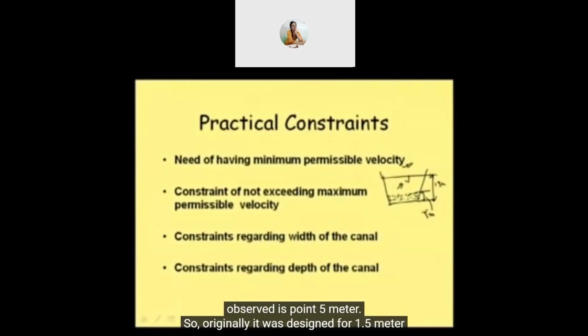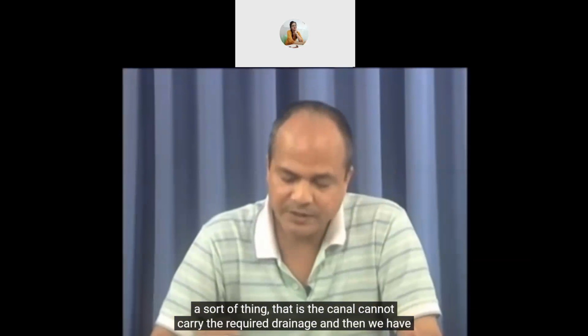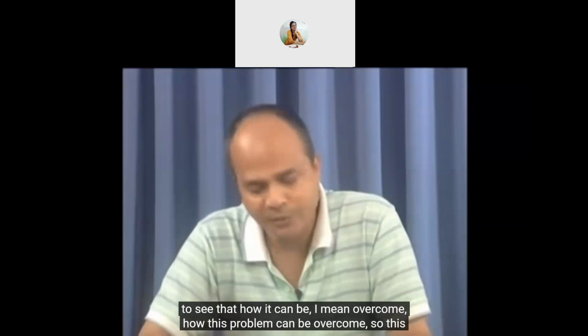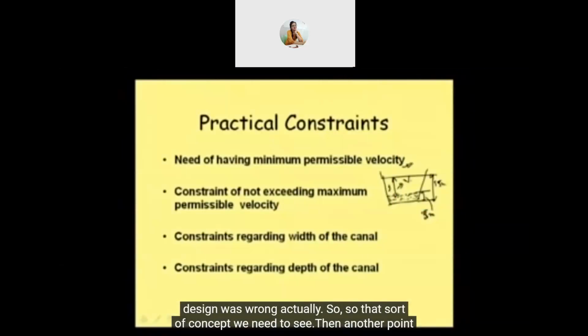So originally it was designed for 1.5 meter of depth, but the existing depth is only 1 meter. So that leads to flash flood sort of things. The canal cannot carry the required drainage, and then we had to see how this problem can be overcome. So this design was actually wrong. That sort of concept we need to see.